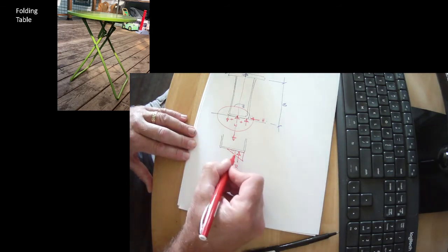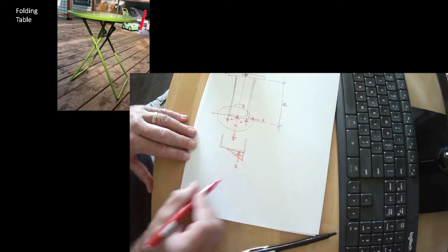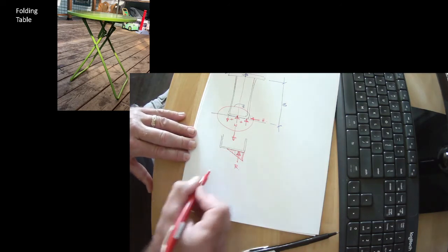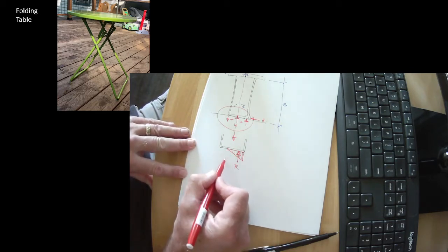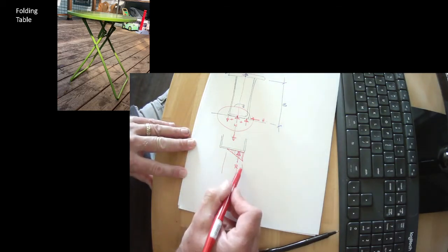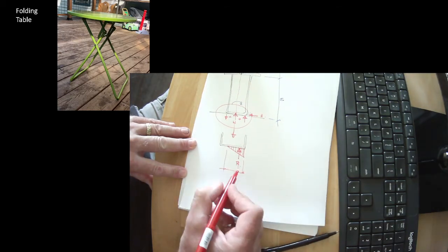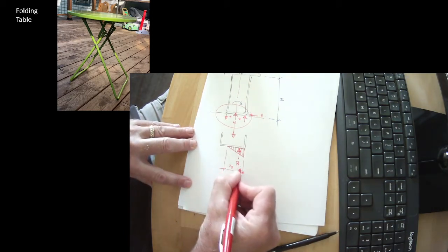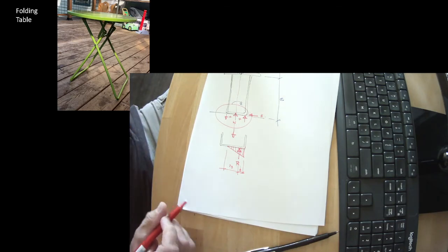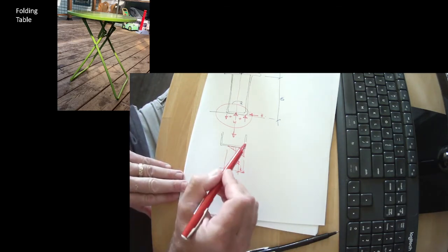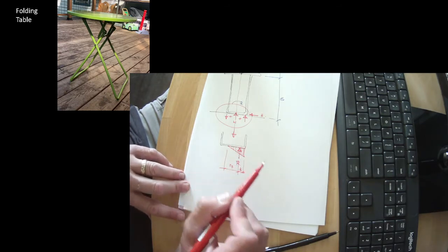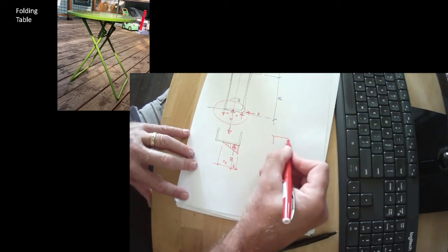And so what we wind up with here is a distributed bearing condition. And just because I've said where I drew the resultant, I know that it's triangular and follows this 1/3, 2/3 relationship. So I figure out where the resultant is, and then I can tell which of those three conditions. Remember, I drew those three conditions.